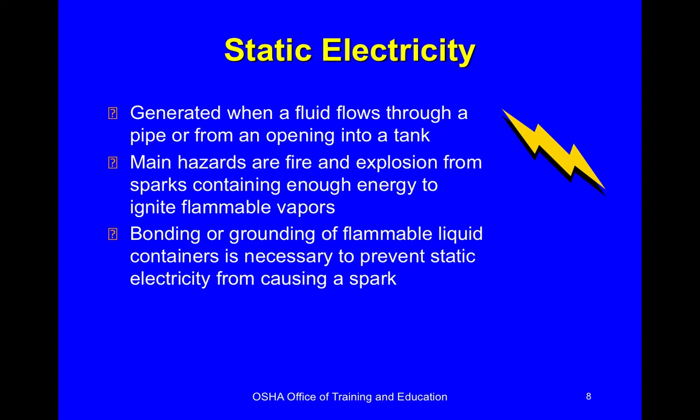Whenever you're transferring a liquid through a pipe or even through an opening, static electricity is generated. And whenever that is generated, it's a positive charge. Whenever it comes in contact with ground, that's when you'll get that arc, that spark, and that would be an ignition source. So static electricity is something that needs to be looked at very closely, and there are ways to minimize the problem.